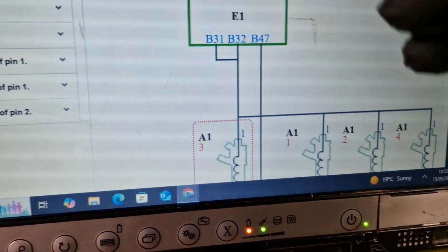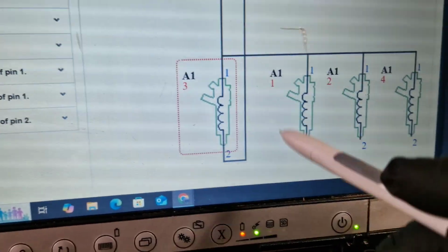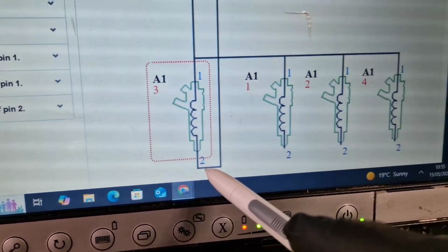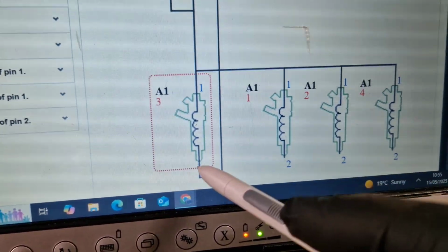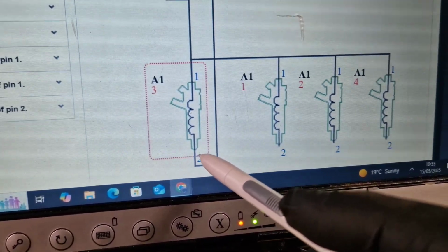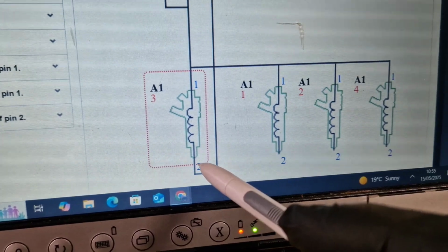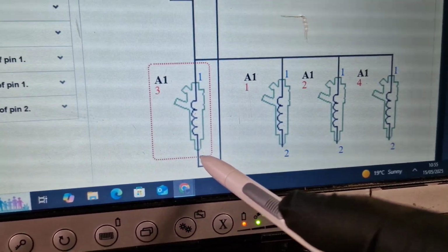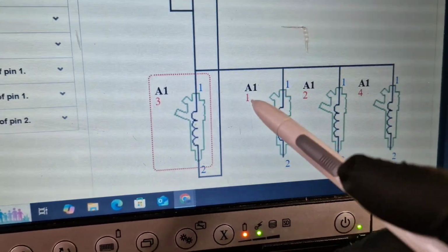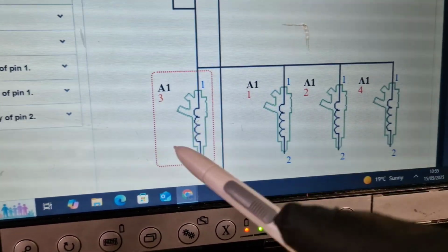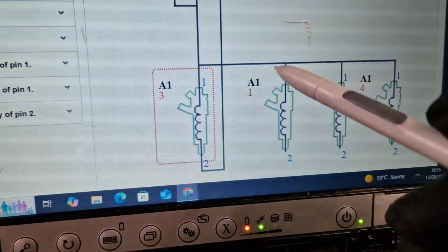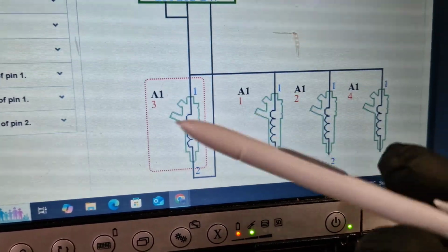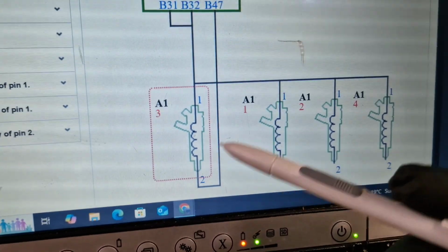So we are going first to take measurement here, and this is going to be the control wire, and we are going to connect the oscilloscope leads. Yellow lead here, or channel 1, and the black lead of the oscilloscope to a good known ground. Then we are going to take the sample or waveform.